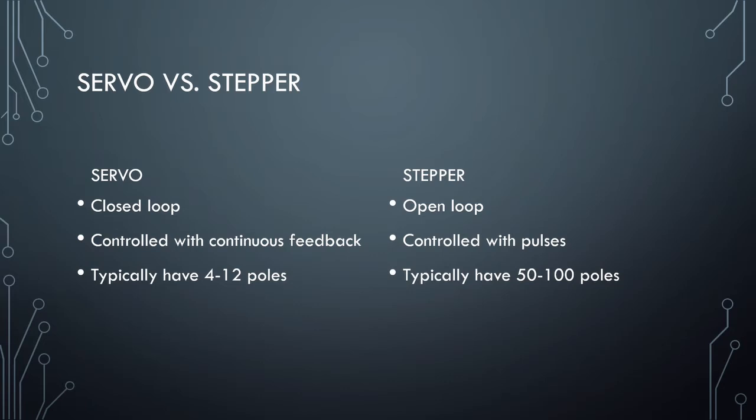You might need that really high precision and high torque or high speed. And in other cases, a simpler stepper motor might work just fine. So if you don't have a lot of vibrations in your environment, you don't need to accelerate very quickly, and a little bit of noise isn't an issue, then a stepper motor might absolutely be appropriate for that application.